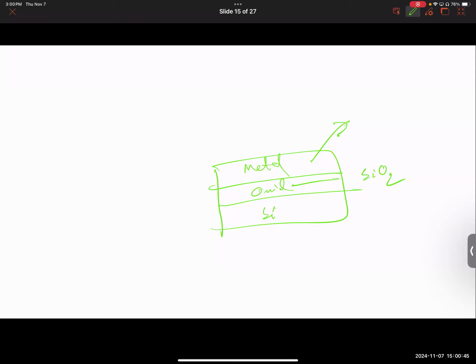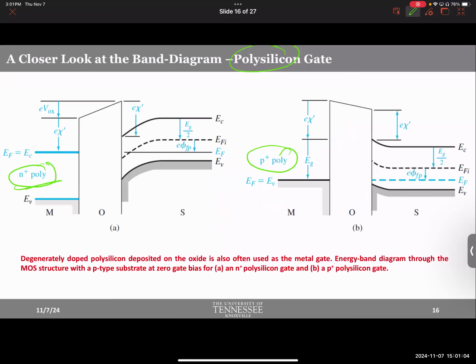So people dealt with these challenges in fabrication. They decided, instead of doing so, let's just use silicon again, which is much easier to have stick on top of silicon oxide. Silicon oxide, silicon. Really nice combination, dealing with only silicons. That was the reason why people used to use polysilicon at some point.